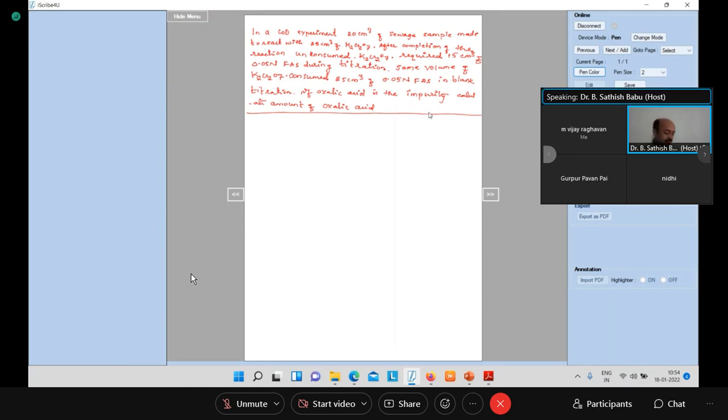Hope you can hear me, right? One of you can unmute and respond. Yes, sir. Okay, so what is the problem? In a COD experiment, 25 cm cube of sewage water is made to react with 25 cm cube of potassium dichromate. After completion of the reaction, unconsumed potassium dichromate required 25 cm cube of 0.05 normal FAS during the titration. The same volume of potassium dichromate consumed 25 cm cube of 0.05 normal FAS in blank titration, and they have given one condition that the impurity present is only oxalic acid. Then you have to find out the amount of oxalic acid present.